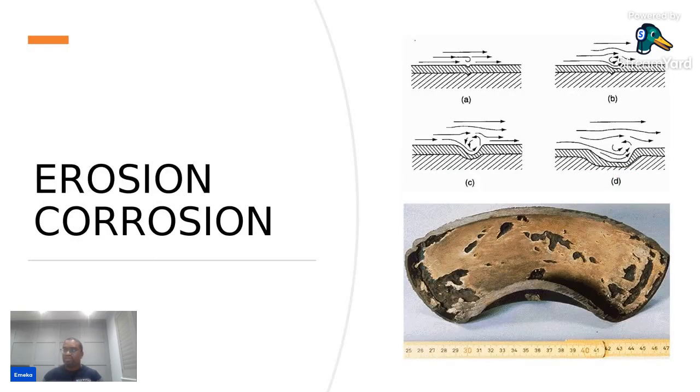To move on, the next and final type of corrosion that we would talk about is erosional corrosion. Erosion corrosion is a degradation of material surface due to mechanical action, often by impinging liquid, abrasion, or particles suspended in the fast-flowing fluid. Erosion is dependent on the process fluid, what the process fluid contains, and also temperature, pressure, and particularly the geometry of the pipework. Where does it occur? It occurs in areas where there are high flow velocity conditions, such as small diameters, reducers, bends, and poorly welded regions, just like the previous picture I showed you about weld corrosion.